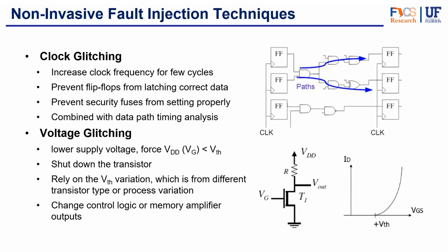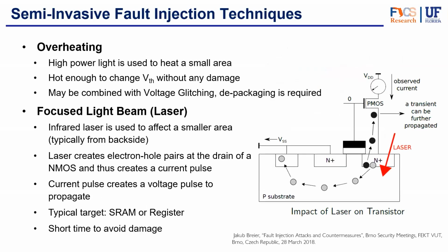They are very easy to apply. They are global attacks, and they are mostly used to change the value of the program counter or loop bounds in the design. Therefore, it translates to skipping some of the security critical operations in the design.